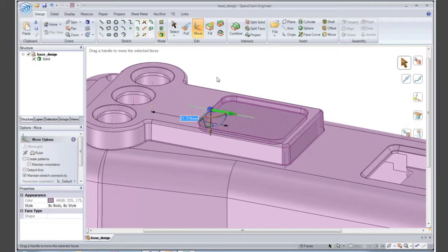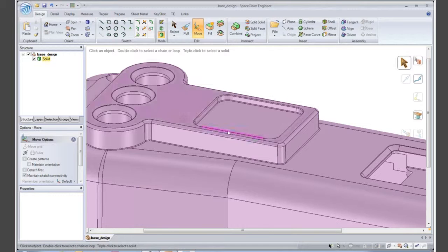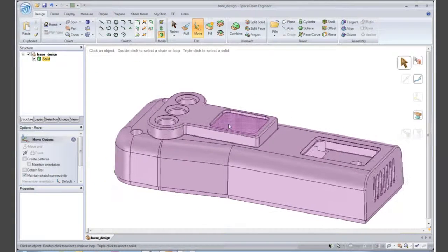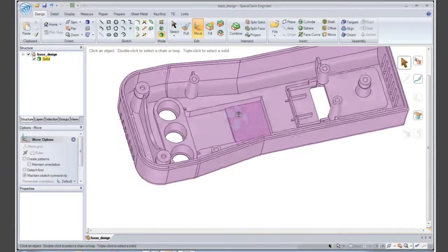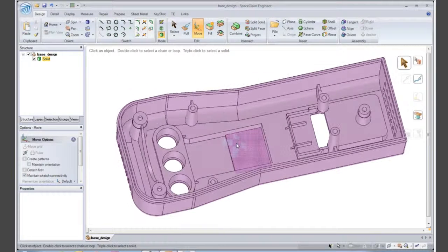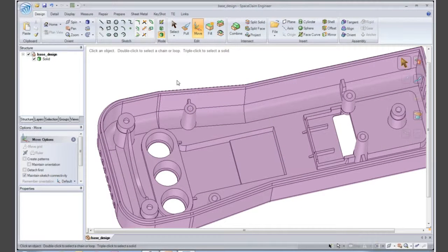And it really doesn't matter what original datum these parts might have been dimensioned to. Just type in any dimension you want and add a parameter or a dimension on the fly. As soon as you see a change in SpaceClaim you want to make, go ahead and make it. You don't have to worry about how the part was originally created or what features were made to do it.